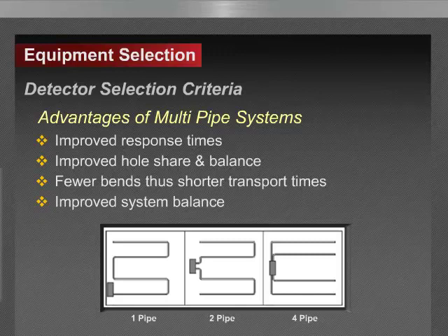So, you take a large area detector that has the potential of multiple pipes, and the idea of using all 4 pipes in such a manner that you break up a much larger space into smaller quadrants per pipe, and the capacity of the pipe depends on the capacity of the detector. Without noting very specific manufacturer's guidelines on maximum pipe, it comes down to the capacity of the detector and what the overall pipe length can be for that given detector.